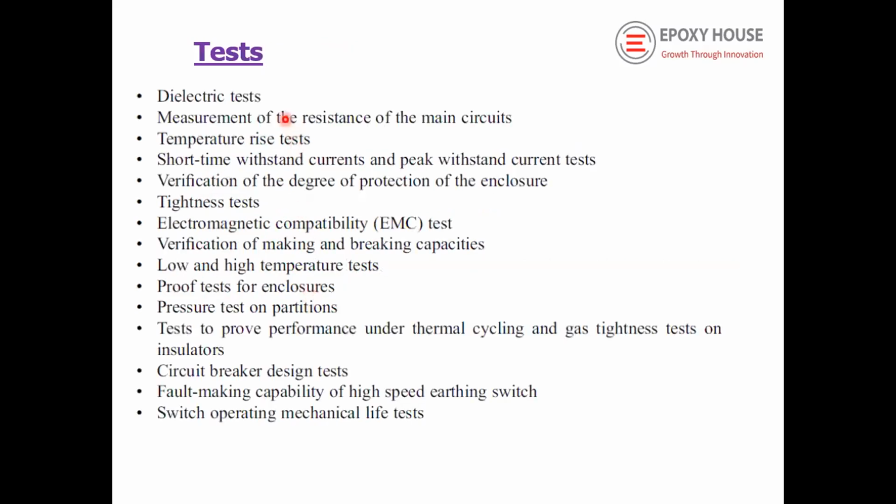These are the type tests. It is not a detailed type test, but a list of type tests as per IEC 62271-203. Electric test, measurement of resistance of the main circuit, temperature rise test, short time withstand test, verification of degree of protection of the enclosure, this IP protection, tightness test on the enclosure, EMC EMI test, verification of making and breaking. This is a very critical test for the breaker and switching elements. Low and high temperature test, proof test for enclosure, pressure test on flat partitions.